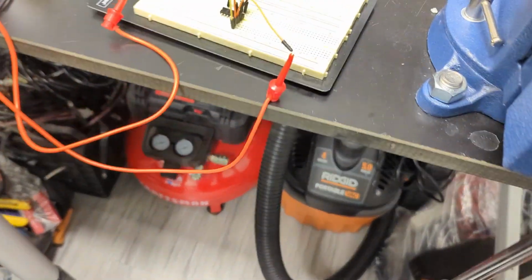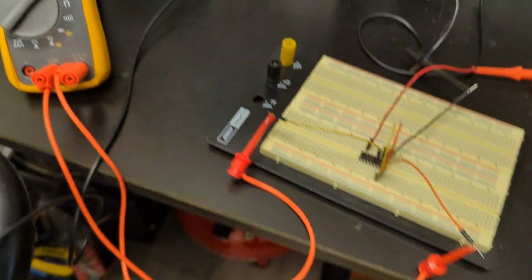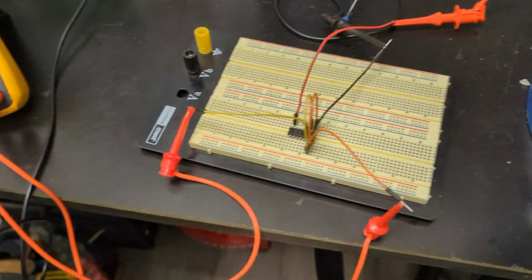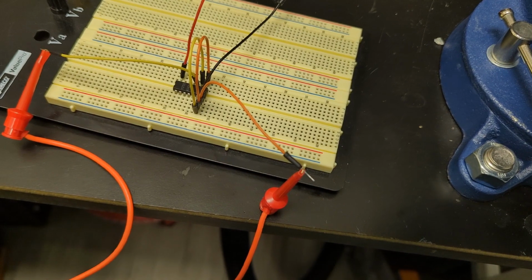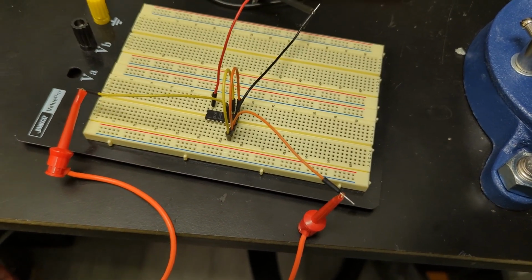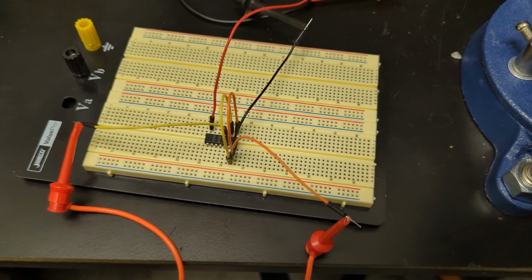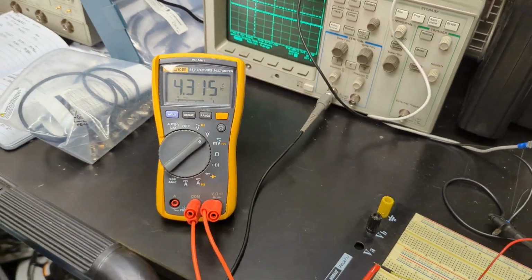And I took a closer look at it. I've got it on this breadboard here. I'm testing it, and it's fine. Right now, everything is tied low on this one gate I was interested in, the one we were looking at with pins 8, 9, and 10. 8 and 9 are the inputs, so I've got them low, and the output should be high, and it is. I tested the other combinations as well. I tested all the gates on here, and they're all fine.